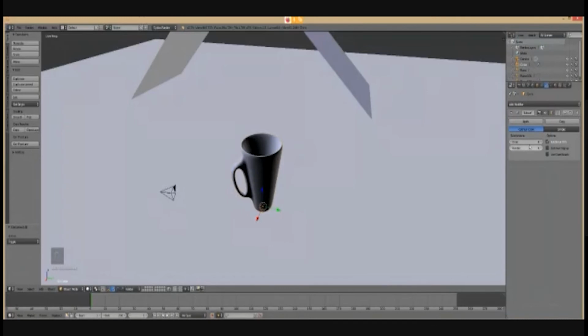So view, if it is at 6, it basically shows me what this would look like at 6. If the render is at 2, then I will be viewing this as very smooth, but when it actually renders, it will be rendering with the value of 2. So it will still look very boxy. So it's important that you change both of them to 6, okay, or whatever high value that you've chosen. And then you can click the apply button.